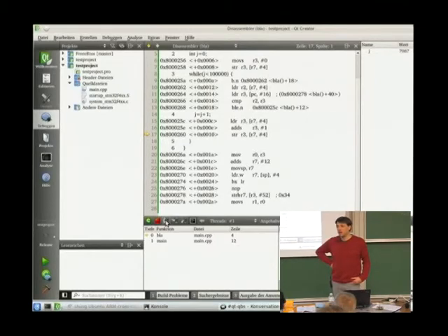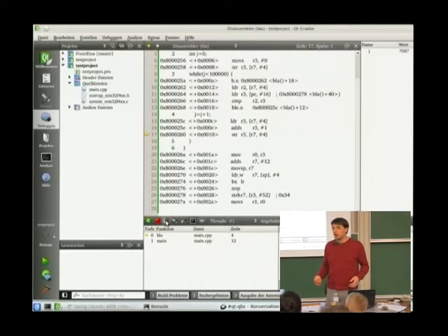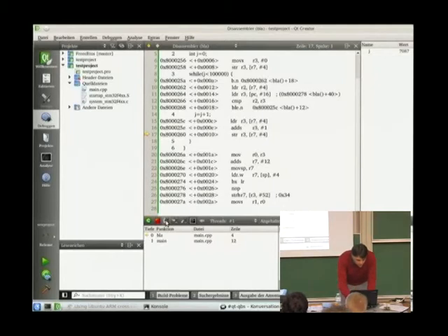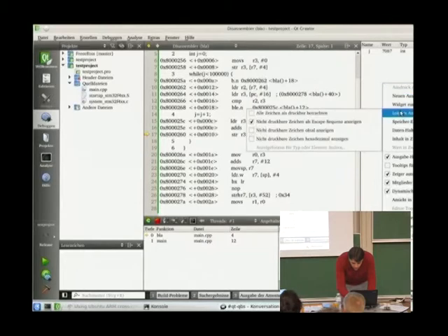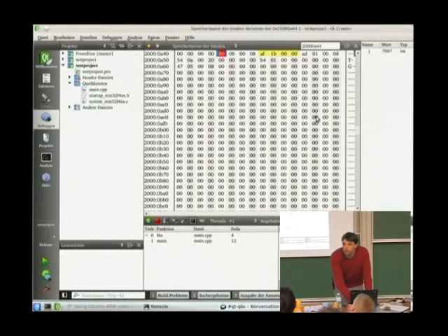Memory map, I don't know. Well, one thing was stuff that you have in device maps. The memory map is an output of the compiler. Yeah. Okay. You can create in Qbs a compiler setting where you just say create me a map, and then it creates a file, and you can just look at it. So well, you got it somehow. I think it means like a memory view of your. Well, that was the question before. But, yeah, not device specific, just a range, for example, an address range. Yes. Yes, you can look into memory via the debugger. So you can, over here, for example, if you want to look at this stack stuff and so on. So that's the debug functionality which is already there from QtCreator in this case.